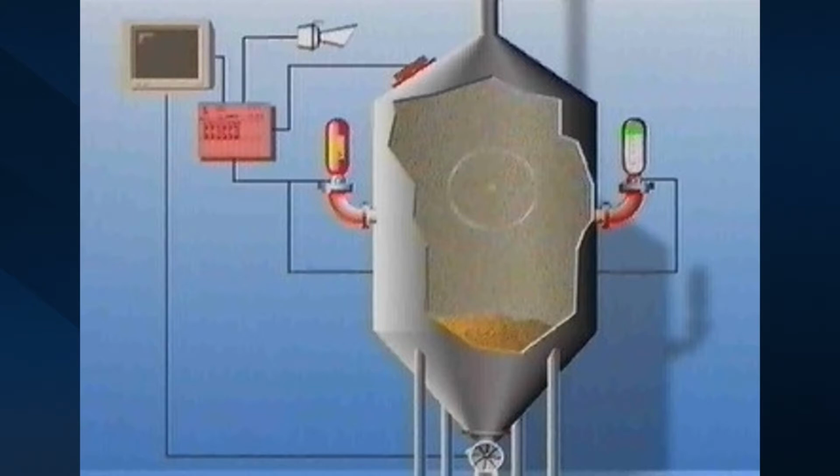So in the next few pictures you'll see how explosion suppression works. If you have an ignition, like you see here, then the starting explosion will emit a pressure wave. The advantage is that the pressure wave goes at 360 meters per second, the speed of sound.